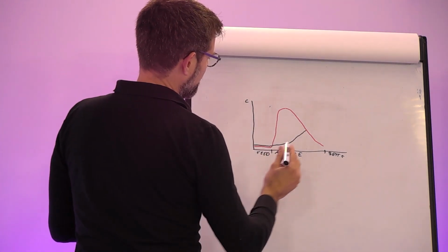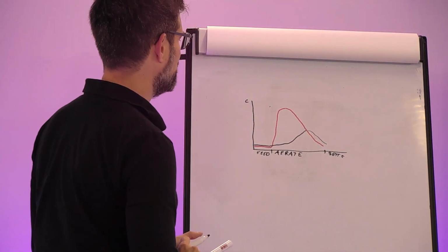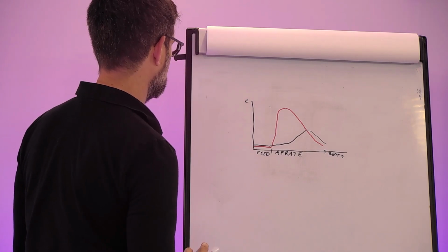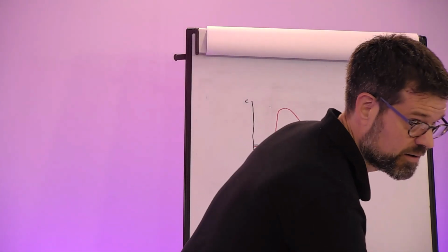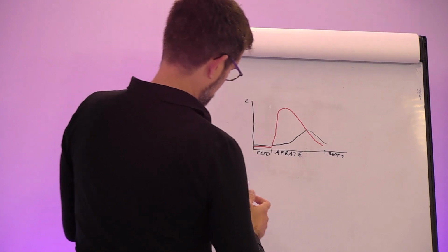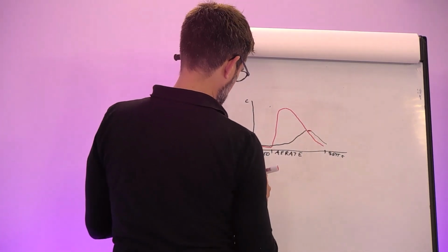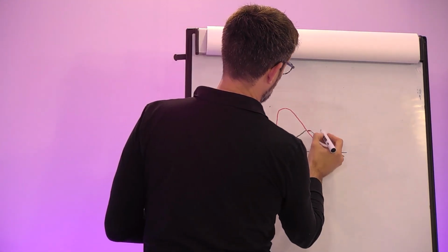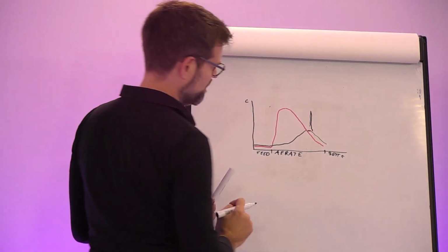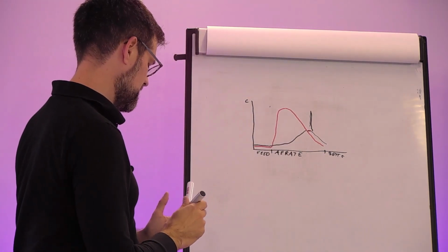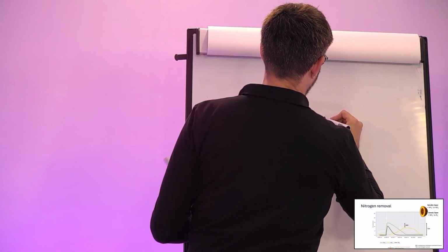And then most of the time we start with a post-denitrification phase to get rid of those nitrates we still build up in the water phase. What you actually see, if we zoom in on the presentation, is that gap: we produce nitrates, but we converted ammonia. So we end up with this part, what we already removed, which we don't see back in nitrates. That's what we call simultaneous nitrification, denitrification, SND.